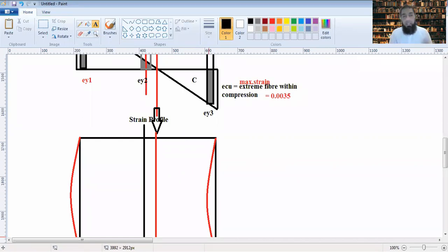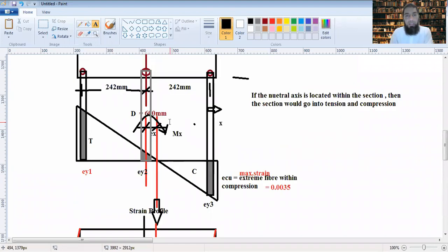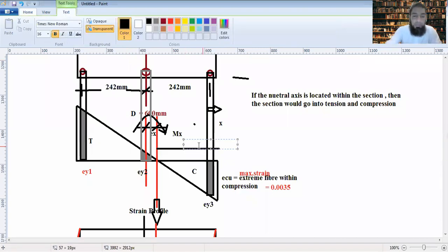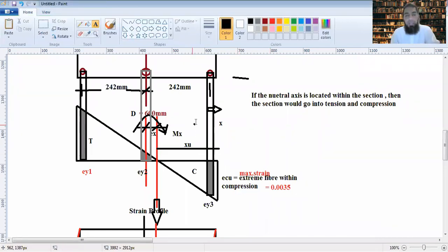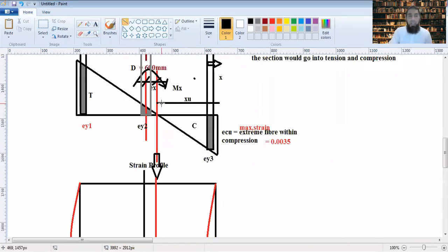And then if now I wanted to check what this is, right from here, this point up till this point, this is XU. It's the depth of the neutral axis. It's somewhat like you are now treating it as a beam. If you reverse it, you can treat it as a beam once it's in the eccentric load, because then half of the portion is coming under compression.